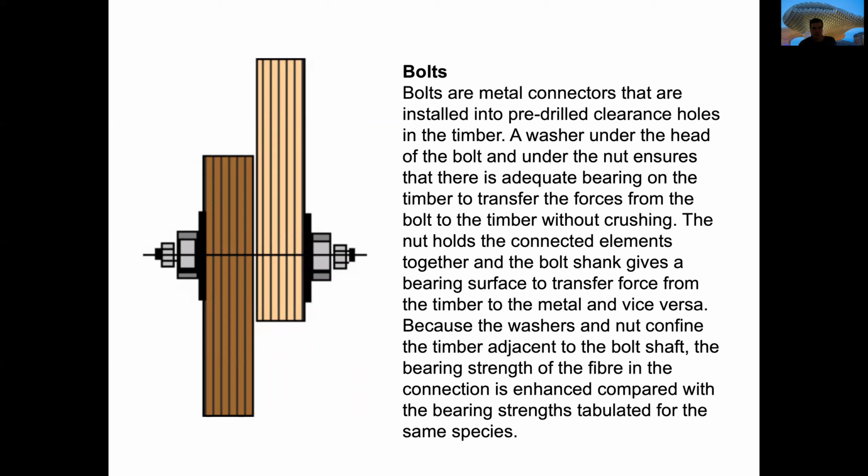The idea of a bolt is that it will create some kind of pressure between the materials and will not allow the material to slice because of the pressure that is created between them. It will also be able to transfer loads from one piece to the other because they will work like one unique piece. Because the washer and the nuts confine the timber adjacent to the bolt shaft.